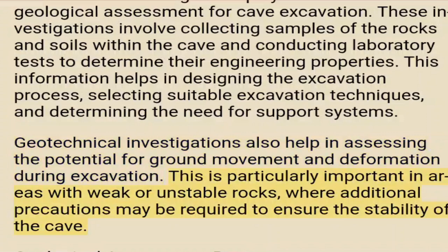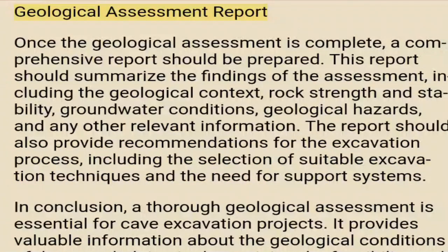stability of the cave. Geological assessment report. Once the geological assessment is complete, a comprehensive report should be prepared. This report should summarize the findings of the assessment, including the geological context, rock strength and stability, groundwater conditions, geological hazards, and any other relevant information. The report should also provide recommendations for the excavation process, including the selection of suitable excavation techniques and the need